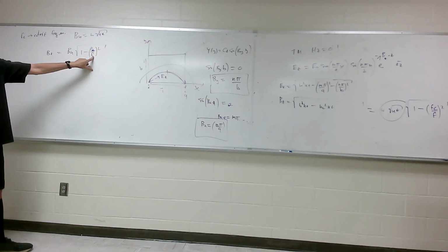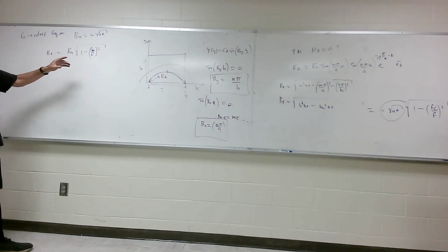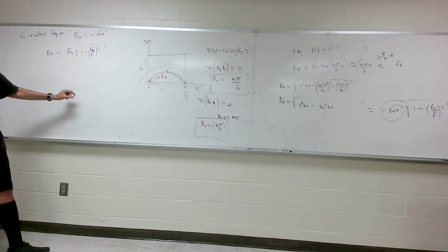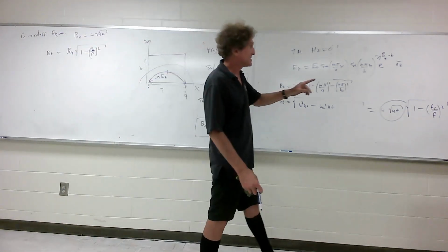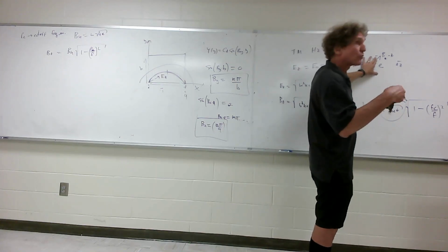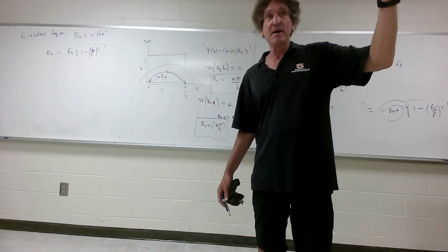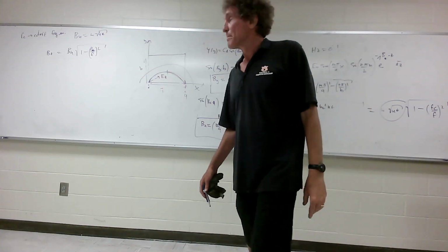If, say, f is 1/2 fc, then this is 2, right? Square it, it would be 4. 1 minus 4 is minus 3. The square root of minus 3 is imaginary, isn't it? When you take a look at the solution, we get minus or plus j times beta as the actual value for beta z, so you see how this is going to actually have a real value, e to the some real value, it attenuates. That's the real truth. It's called an evanescent wave, it'll just decay to 0 very quickly. That's why it's called cutoff.